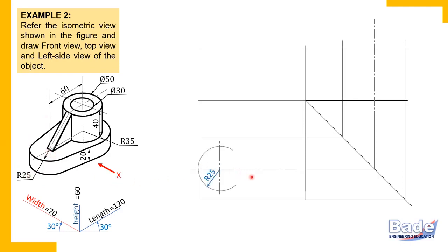So take that radius 25 and draw the curved edge. But wait, don't draw a complete circle, because this is not a complete circle. It is a portion of a circle of radius 25. How much portion of this circle is the edge of the shape, we are not sure about that. That is why don't make this curve dark at this stage.